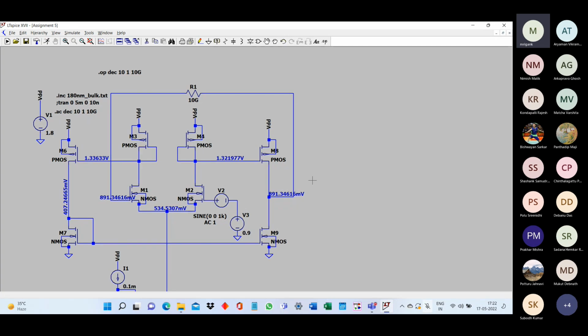We just have the feedback voltage at the negative terminal, which subtracts from the input voltage. So it is voltage sensing, voltage feedback, which means shunt at the output and series at the input.